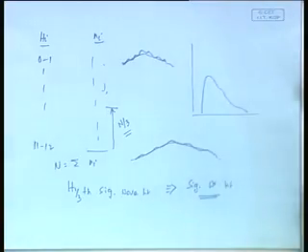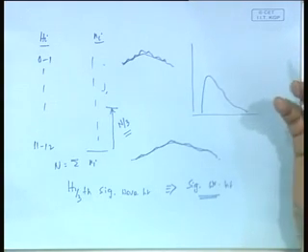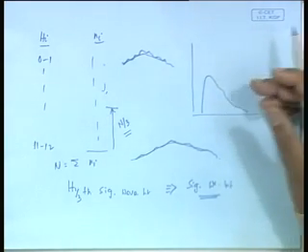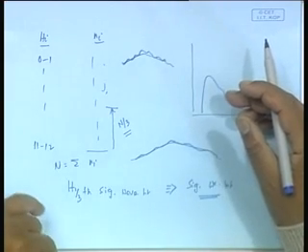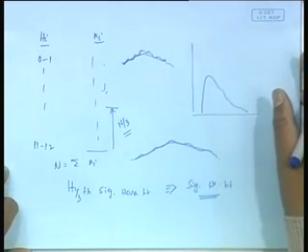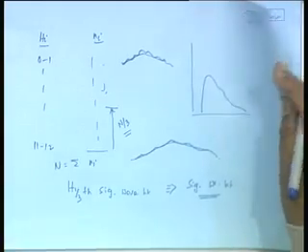So, if I count them and use them for the average, the average tends to get pulled down to the lower side. You might end up getting an average of say 2.5 meter, when the significant wave height would be 3.2 meter. As a result, the term significant wave height is more used. That is a very important concept, because in almost all of our subject we always use significant wave height, not average wave height.